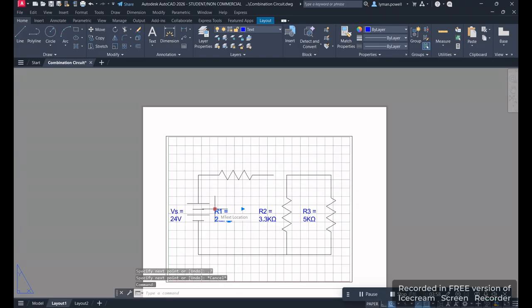So we're going to just click on our label and again click on the square and drag it up to the center of our resistor. Now it looks a little small, and we don't need it to be two lines. So if you click on the arrow up here, you can drag it out and make it all in one line. And then you can move it down to where it is fairly centered with our resistor. And then we have to hit escape to undo this.